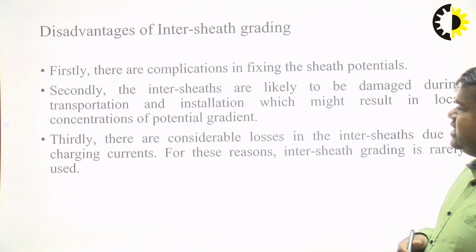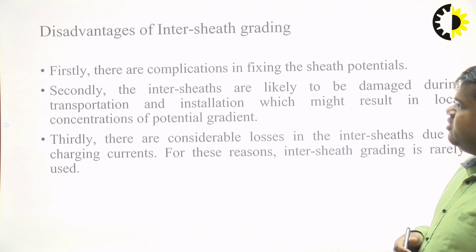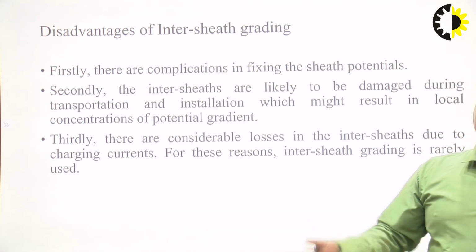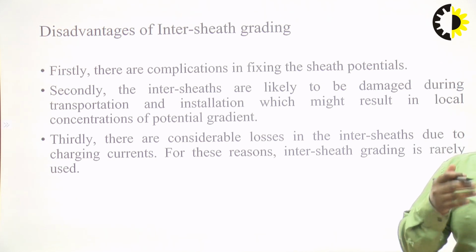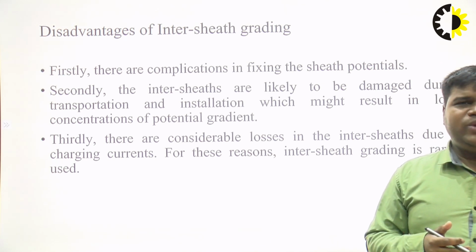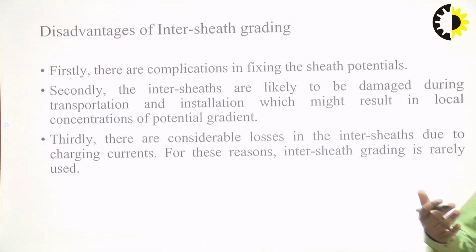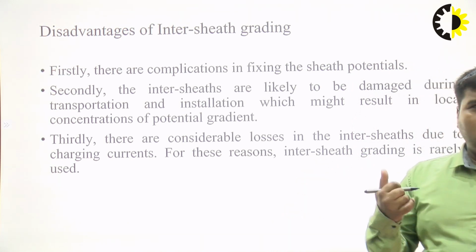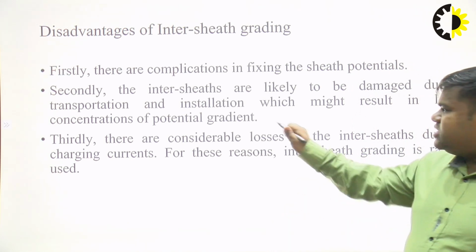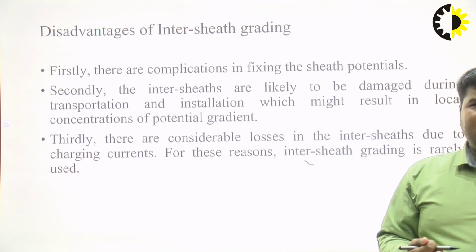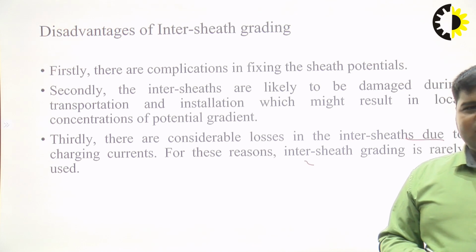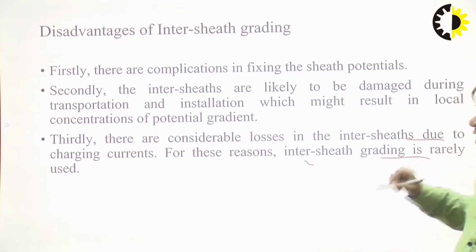Now the disadvantages of intersheet grading. Firstly, there are complications in fixing the sheet potentials V1, V2, V3, and correspondingly the gradient. Secondly, the intersheets are likely to be damaged during transportation and installation, which might result in local concentration of potential gradient. Thirdly, there are considerable losses in intersheets due to the charging currents. For these reasons, intersheet grading is rarely used.